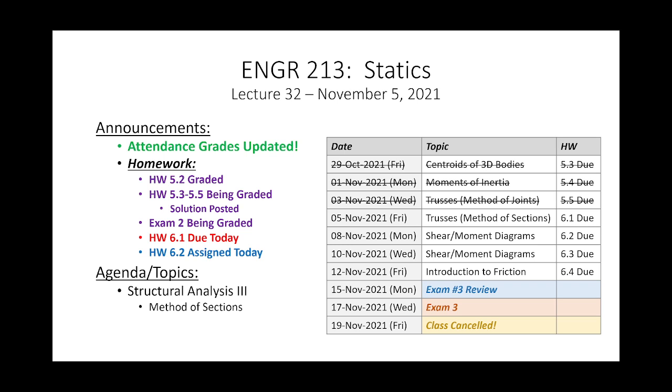But I would argue that if there's any one way of illustrating the method of joints, it's tedious but thorough, and it does require accurate bookkeeping. It's really easy to switch an arrow around and mess up your calcs. I think one advantage of the method of sections is that with it, there's very little possibility that an arrow gets flipped, because you're only looking at one cross section.